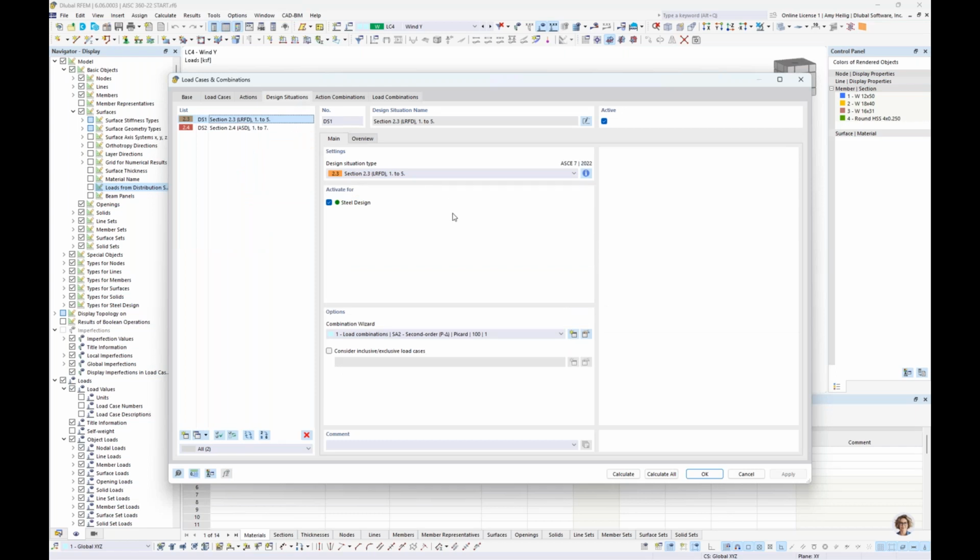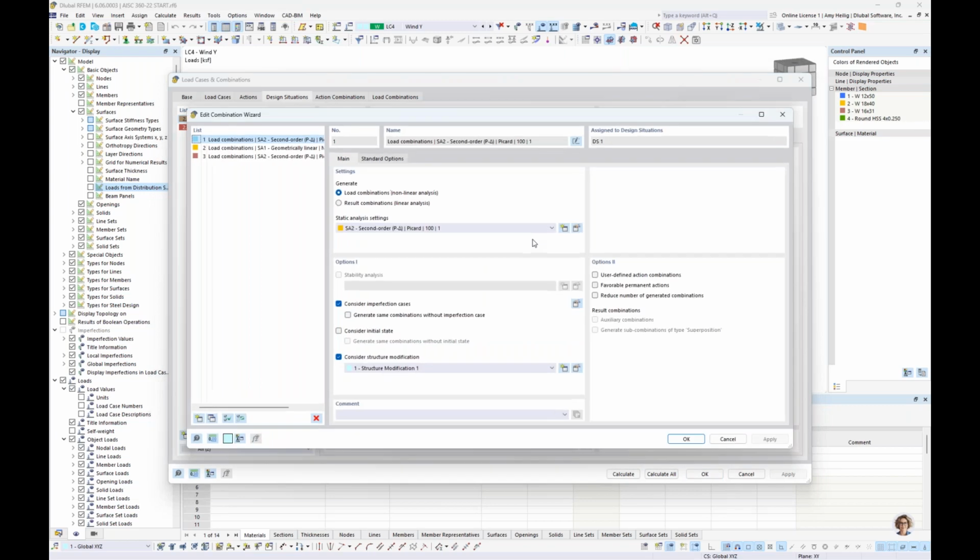Now, I do want to cover a few requirements from Chapter C, the direct analysis method. We don't have time to go into much detail today, but if you refer back to a previously recorded webinar, AISC 360 2016 steel member design on our website and on our YouTube channel, I go through the requirements of Chapter C in much more detail. But for today, it should be known that under the combination wizard, if we take a look at this definition type here, that these load combinations will be run automatically according to a second order analysis. So we are considering both big P delta and little p delta automatically for the second order analysis.